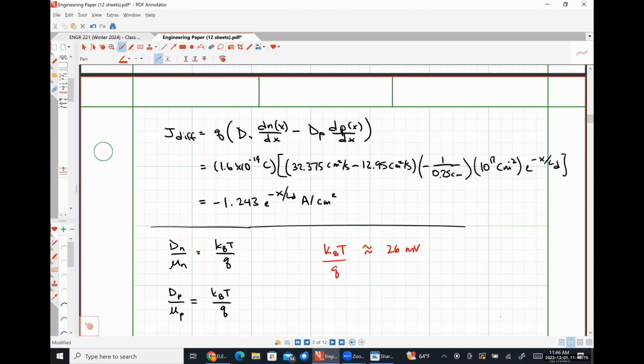So there's a thing called electromigration, which effectively means if you try to push too much current through a trace that's too small, it melts or distorts the trace. We're not really going to worry about that too much in the context of this class, but if you choose to go look at the integrated circuits class next year, that will be a thing. For the most part, at least in electrical engineering 335, I'm only going to be really concerned about discrete electronic circuits, meaning that it's made of physical transistors, resistors, capacitors, and all of that kind of stuff to form a circuit, so you could breadboard it.